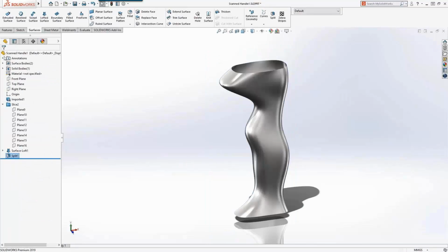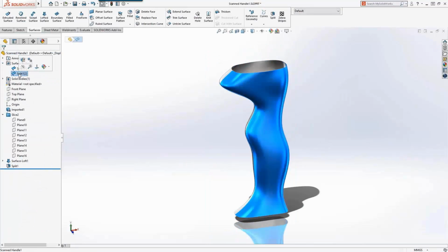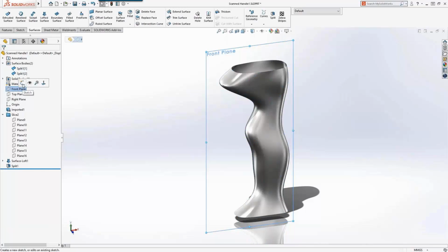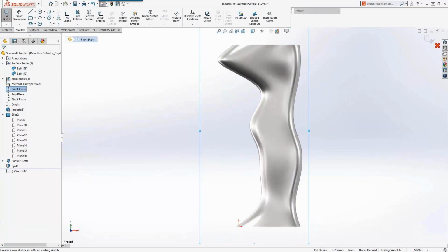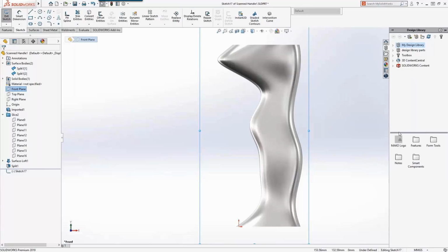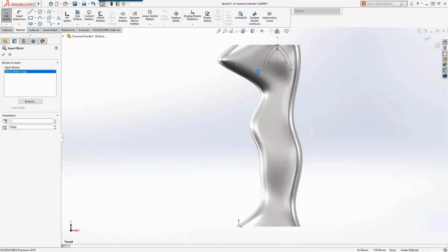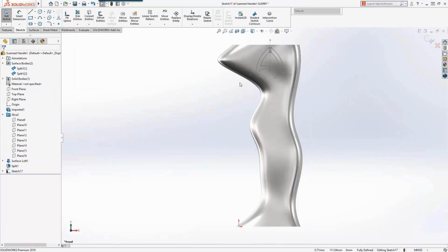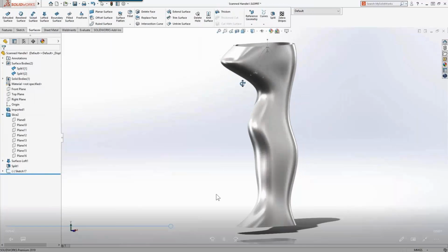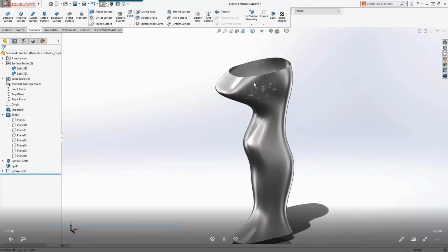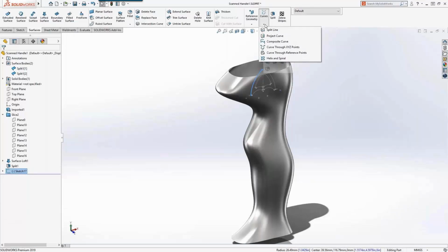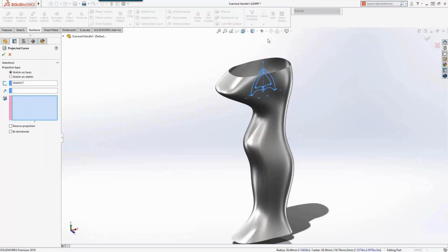This handle will be designed into two halves. So to continue the design workflow, the split command can be used to create two bodies split at the center plane. A logo needed to be applied on each of the halves, so the sketch will be created and the sketch block will be applied to and positioned from the design library.